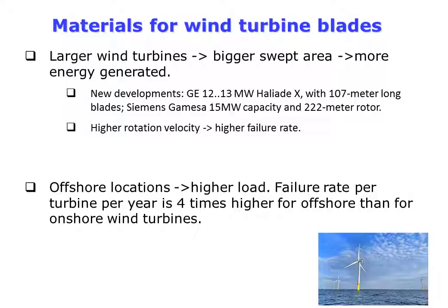A few decades ago, most of offshore wind turbines of the world were located in limited area between Scotland, Hamburg, Denmark, and Norway. Now, wind parks are built in monsoon area, in Far East, in hot area near India and Arabic Peninsula, in North Sea. These locations are not very maintenance friendly. The winds are stronger. Monsoon and typhoons represent additional loads. Larger rotor means bigger swept area, and more energy generated, but also, higher blade tip velocity, and more surface degradation.